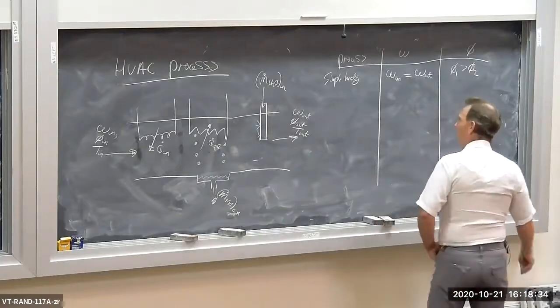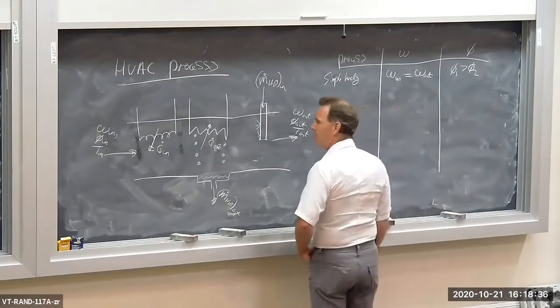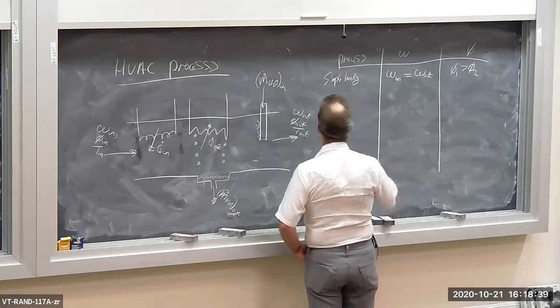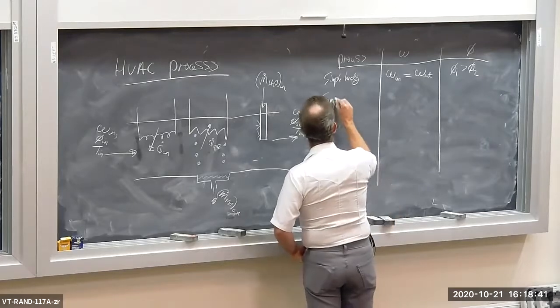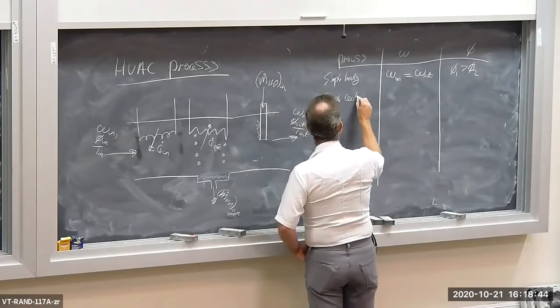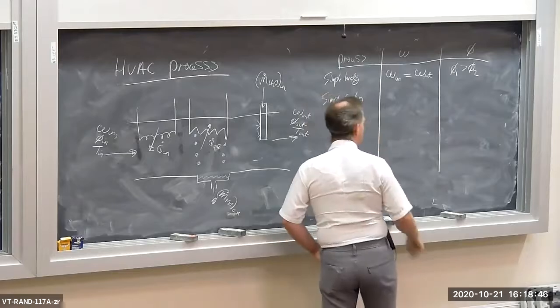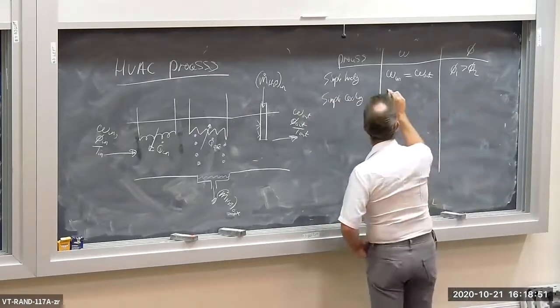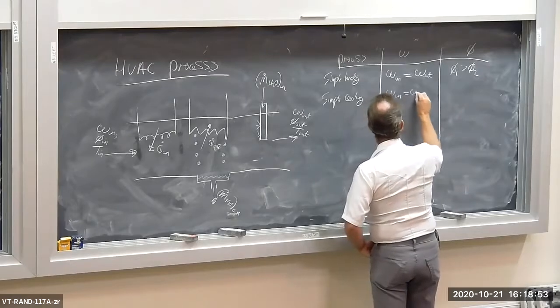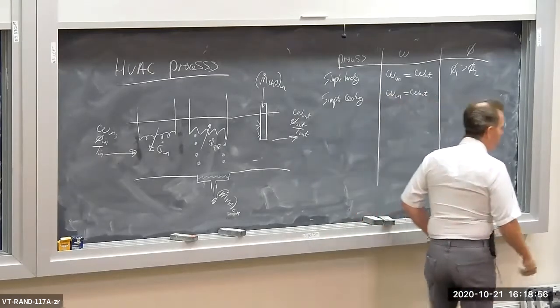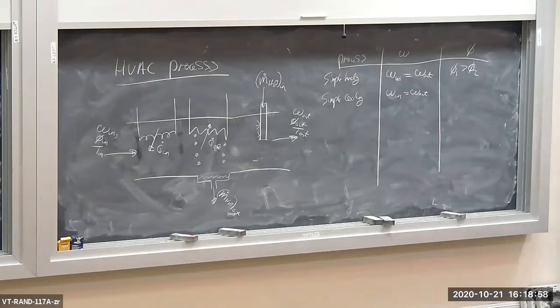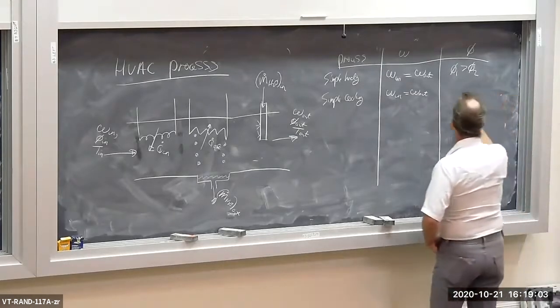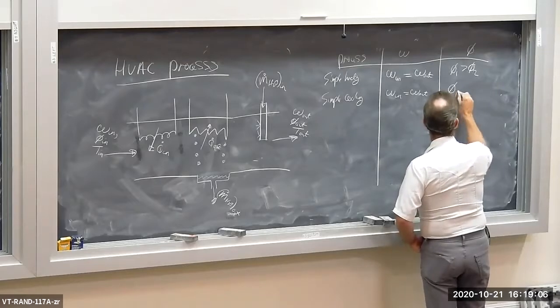Okay? Now, what about simple cooling? That's where we're extracting heat, but we're not extracting any H2O. So simple cooling. Well, again, we're not adding or subtracting any H2O. So omega in is equal to omega out. But now the air is colder at the outlet compared to the inlet. So the outlet relative humidity is greater than the inlet relative humidity.